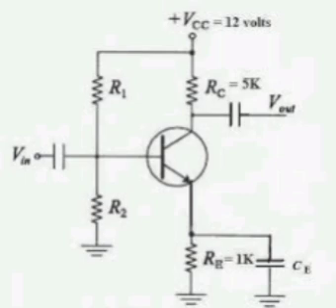Line energy of dislocation equal to half G b square equal to half of 80.2 into 10 power 9 into (2.485 into 10 power minus 10) whole square, that equal 2.476 into 10 power minus 9 joules per meter.